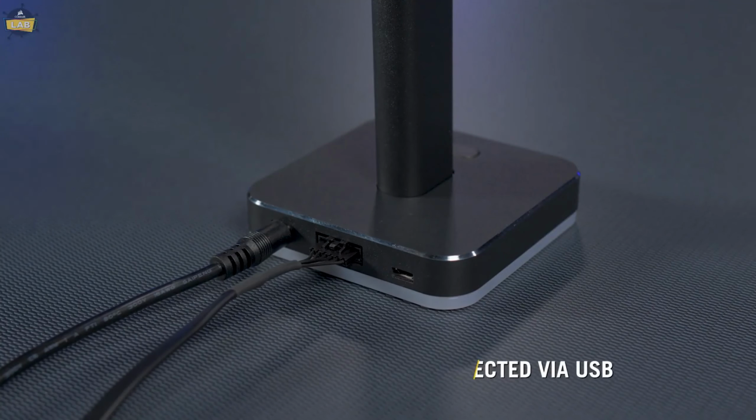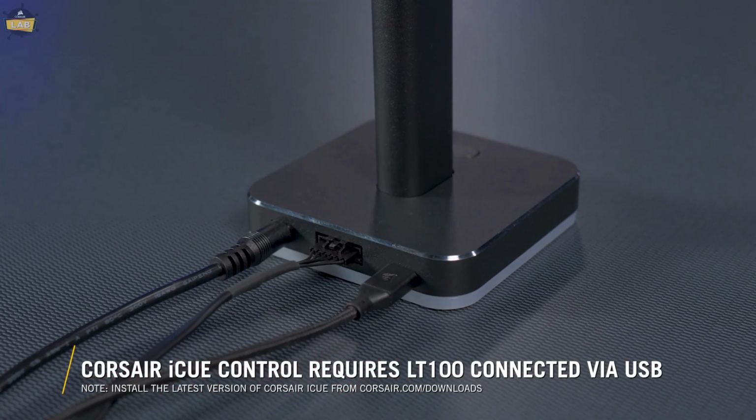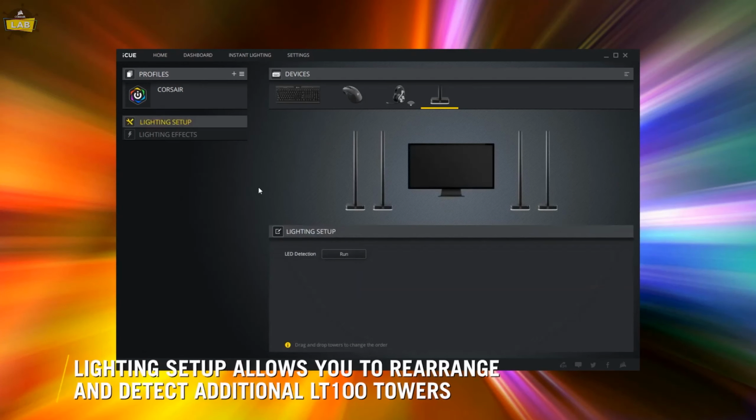To control your LT100 starter kit with Corsair iCUE, plug the provided micro USB cable into the base of the main LT100 tower and connect the other end to an available USB-A port on your system. Download or update to the latest version of Corsair iCUE. Click on the tile for your LT100 starter kit and proceed to lighting setup. Click the Run button to proceed with LED detection in iCUE to ensure each tower is detected correctly.